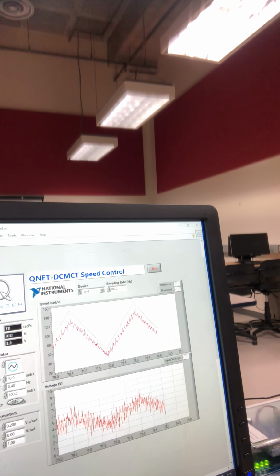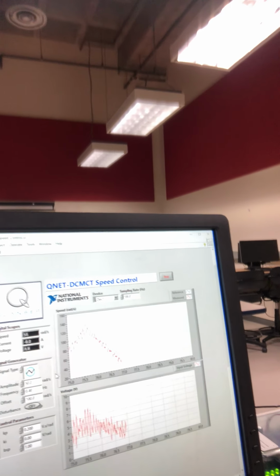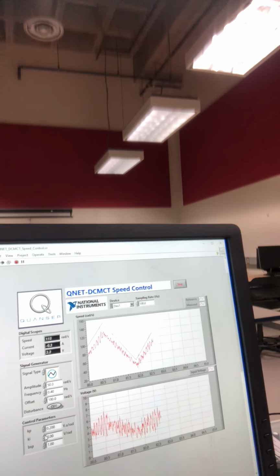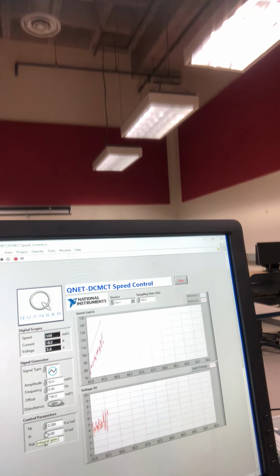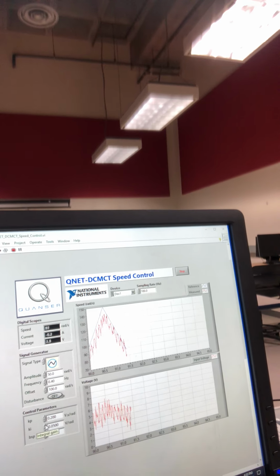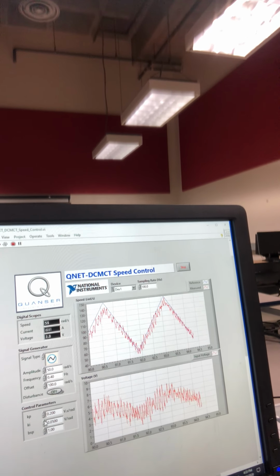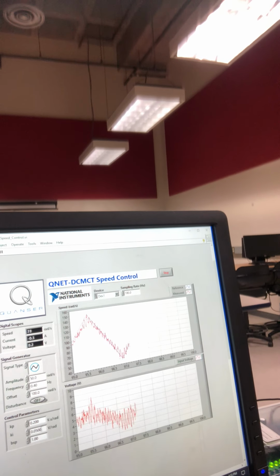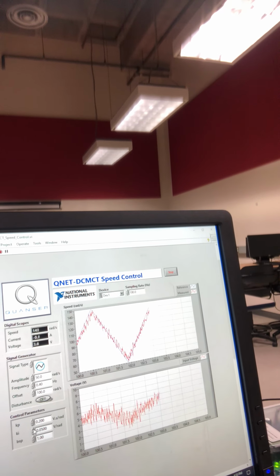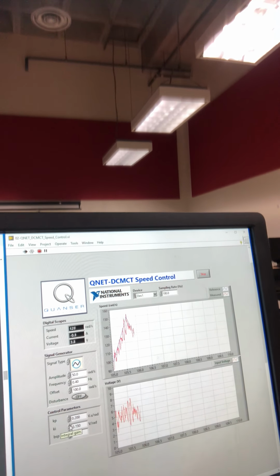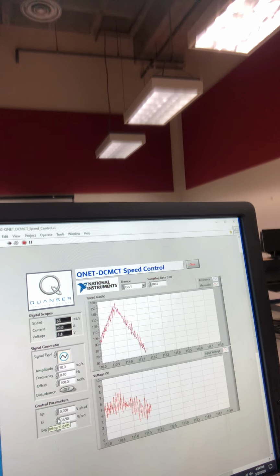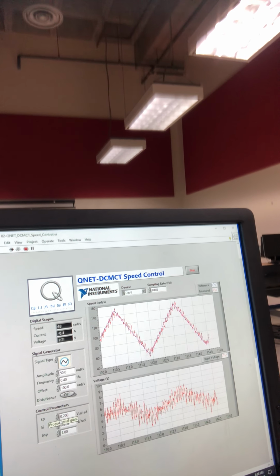You can see right now the real response almost matches the reference. The difference comes from Ki. We have to increase Ki to integrate through that difference. You can see even a small Ki can overcome that difference. And when we increase it, it matches better right now.